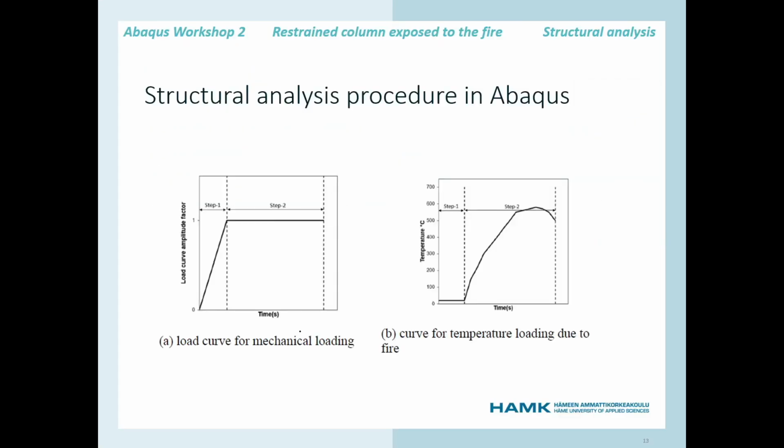So in the structural analysis, here we have two steps. The first one is step 1, which is the mechanical loading step, and the second step is the temperature loading step. So we have this fire heating step. Now here the loading is initially 0 at 0,